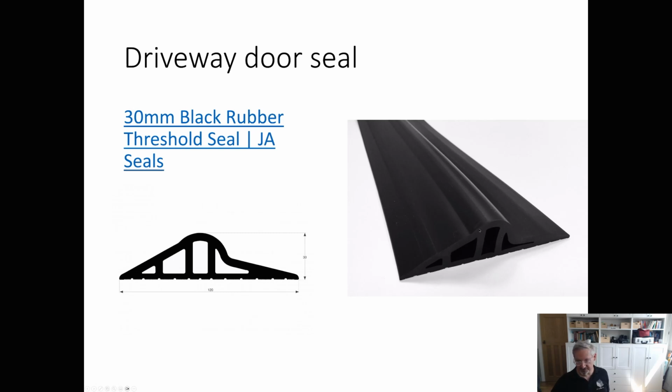Looking at the door seals, I'm looking at things like this to seal the doors, which give us nearly 2 inches, 1.5 inches, 1 inch and a bit, and then building up from there on this side. So basically this will be the ramp section in, and instead of dropping back down, we'll actually have insulation and boarding on top of the concrete that exists.